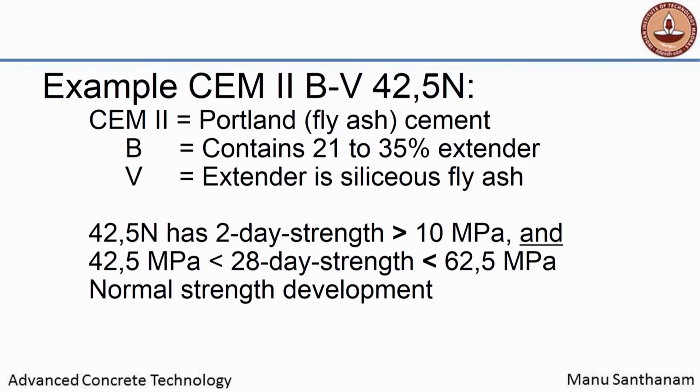Now, in EN standards there is no performance based specification like in the ASTM standards. There, ASTM has taken a step forward and given a very challenging scenario to the cement producers, that they can actually come up with cements that match performance requirements, and that is a very interesting move because now it permits all kinds of combinations. But then again you need to have the backup data to show that those combinations will actually lead to that performance being achieved in concrete, and that is a very challenging thing to do.